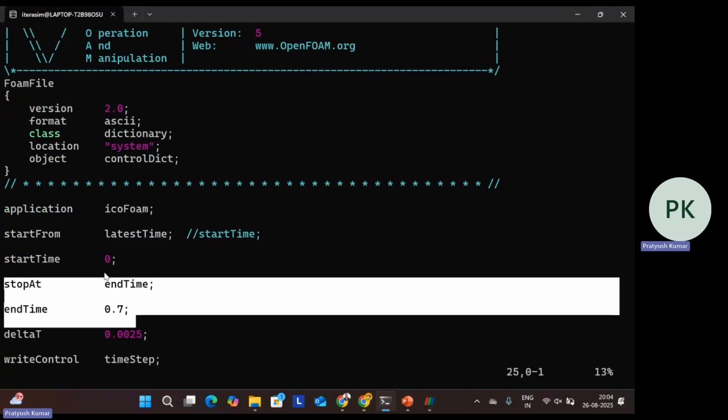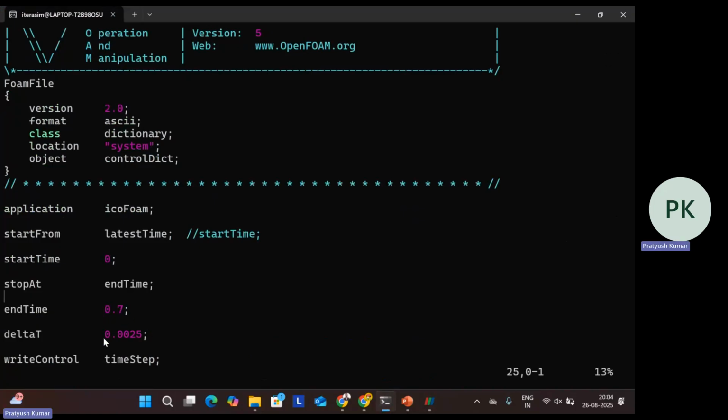So in that scenario, these steps, 0.1, 0.001, 0.002, are the number of iterations. There is no value of time in steady state. But if we are speaking of a transient solution, then it is time, in seconds. So it will start from 0. It will take delta t equal to 0.0025. So after 0, the next time will be 0.0025, then again 0.005. Got it? So this is the delta t that is followed.